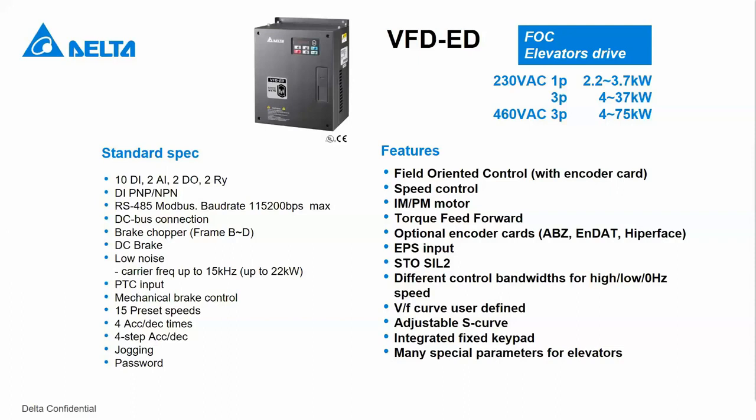And the drive can control that. So the drive can move the cart to the closest floor in order for its passengers to be able to get out. And it also supports typical encoders which you find in elevator applications, such as EnDat and HIPERFACE. And of course, some other typical functions like torque feed forward, which means that if you note a loading on the motor, then when you release the mechanical brake, you can apply a torque feed forward in such a way that there will be a very smooth release.